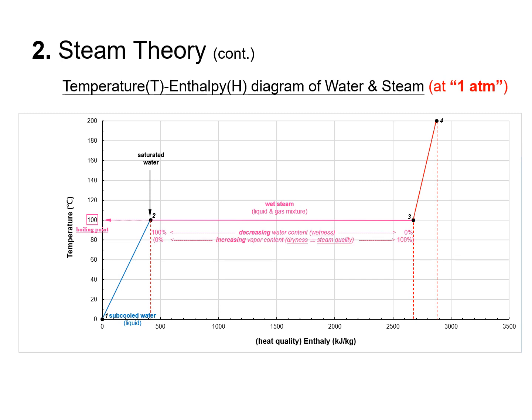Or we can say the dryness of the mixture, defined as the steam quality of the wet steam mixture, increases from 0% to 100%. At point 3, there is no liquid water content in the steam. Its steam quality is 100%, and it has been fully transformed into dry saturated steam. When additional heat is applied above the boiling point temperature, it will, in turn, continue to increase the temperature of the steam. This dry steam is referred to as superheated.